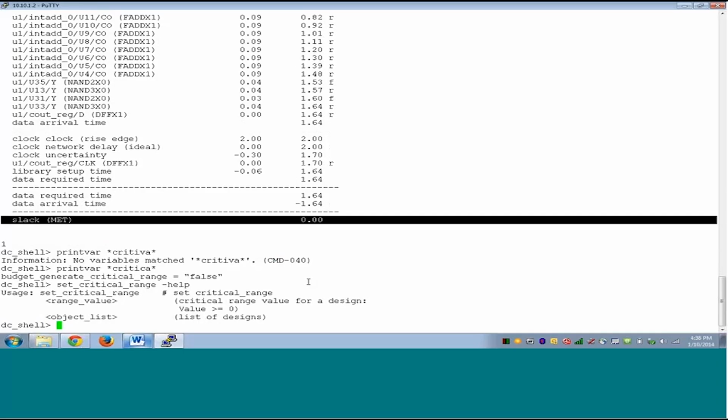Now, DC will optimize, and we have seen that it uses multiple iterations to do timing optimization, to do everything. By default, when you do not issue any special command, DC will try and fix from the worst paths that are violated. It will then do area recovery, so it will focus its energy on the worst violators, for which the slack is less than 0.